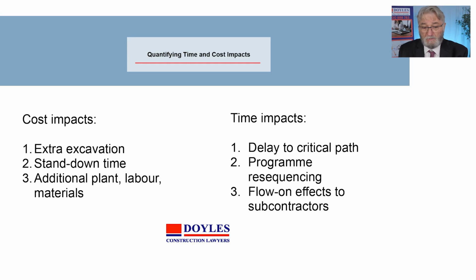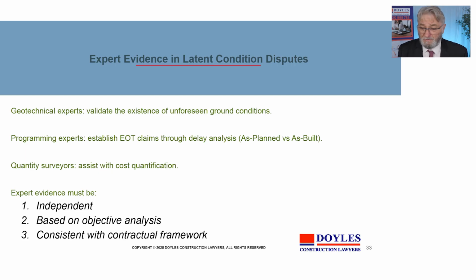It's important to make sure that you prepare claims in the geotech particularly, but other latent condition claims, so that they're effectively waterproof. Looking at those aspects, you want your geotechs to validate the existence. It's not a matter of saying, oh, I hit rock. No, get a geotech to say what rock you hit. Programming experts to show what's happened as a result of that latent condition, and quantity surveyors to assist in the cost quantification. Oftentimes an expert quantity surveyor can prove a level of cost that's substantially above what your site foreman might claim. But you want expert evidence which is independent because it stands the test of time better.